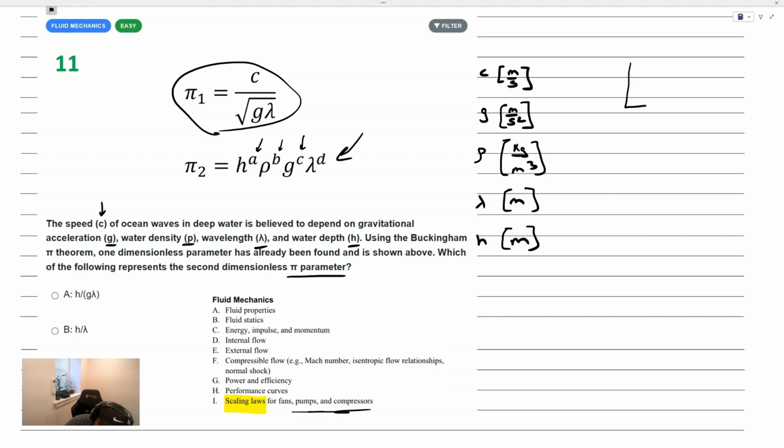If you think about the idea of the Reynolds number or the Moody chart, we have a dimensionless axis here where the y-axis is the friction factor, the x-axis is the Reynolds number. There are different lines over here of relative roughness, right? All of these terms are dimensionless and they're fully able to characterize any pipe material, speed, diameter, viscosity, flow rate. It's not 100 different charts. It's a single chart put on one piece of paper. And that is the application. That's the power of the Buckingham pi theorem.